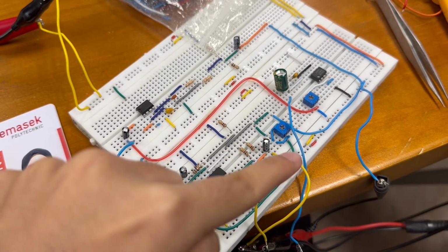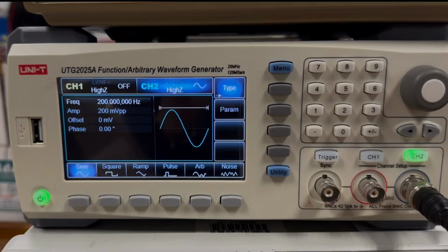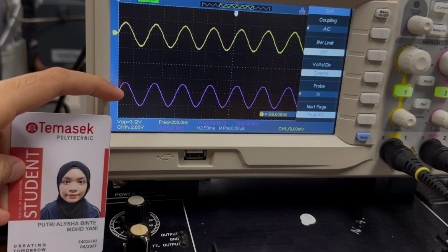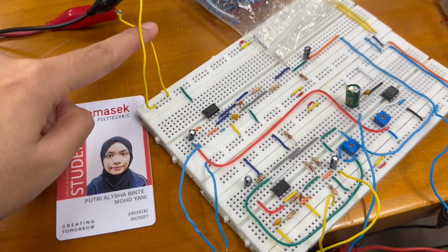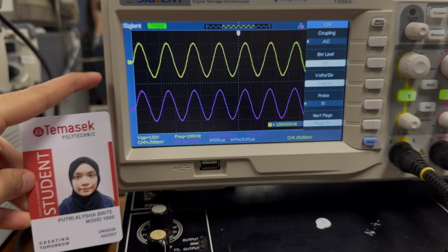So for the last stage, it is a power amplifier, so the input and output should be somewhat similar. So this is the 9 volts and this is for 200 Hz, 200 mVpp. So both input and output should be in phase and should be around the same values, which over here is around 3 volts. Still at the last stage, the only difference is that the frequency has increased to 1 kHz. Now the input and output should still be in phase. However, because it is an increase of frequency, the input and output have now both decreased together to around 1 volt instead of 3 volts. Now still following the previous stage values.